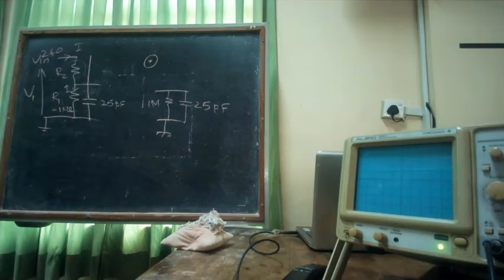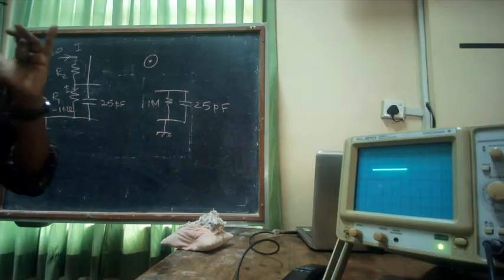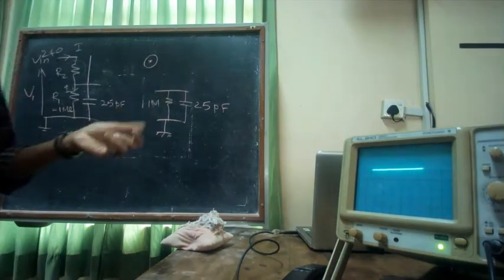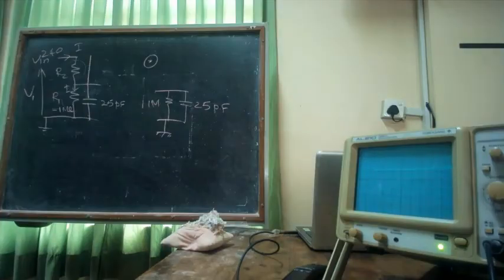So what about that? Now, I said high frequencies. At very high frequencies, capacitors are like short circuits. They like to go through. We will learn this later, right? But resistors, they don't care whether it is high frequency or DC. The same thing. They will be very faithful.